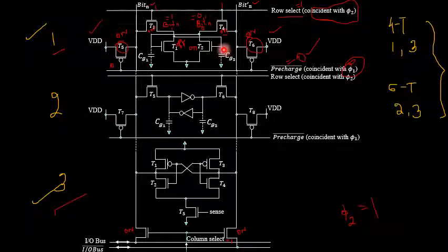So whatever the charge is stored in this particular capacitance. If a 1 was stored, that is, this particular bit n value was equal to logical 1 state, then through the capacitor Cg2, since the transistor T2 is on, via transistor T3, that will be read through your bit line, that is the bit n signal. Similarly, if this particular bit n value was 0 and bit n complement was equal to 1, then that value will be read through the bit n complement signal, through the charge which is stored in the capacitor Cg1. So from the capacitor to the bus, it is performing a read operation.